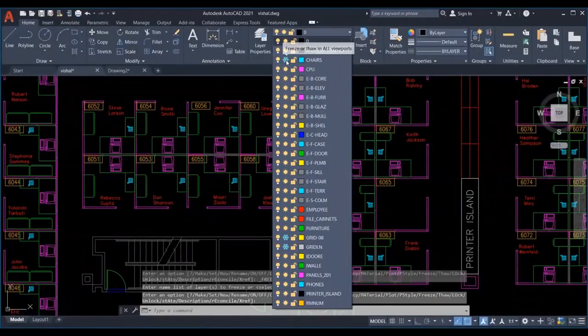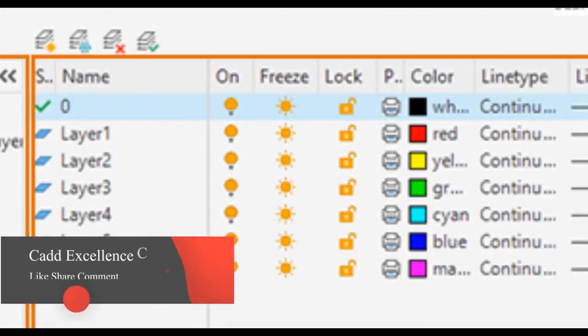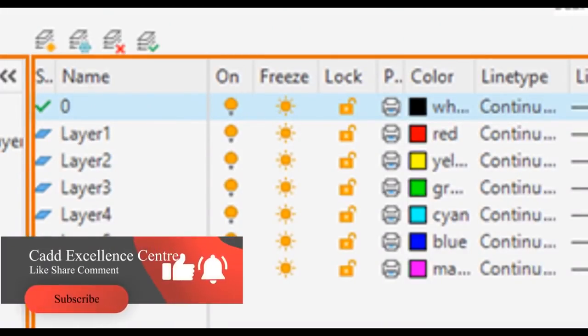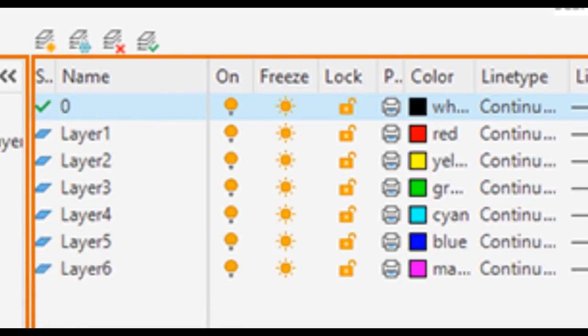This freezes the selected layers. You can freeze layers to improve performance and reduce regeneration time in complex drawings. Objects on frozen layers are not displayed, plotted, or regenerated. In drawings that support 3D modeling, frozen layers are not rendered. Not applicable to AutoCAD LT.